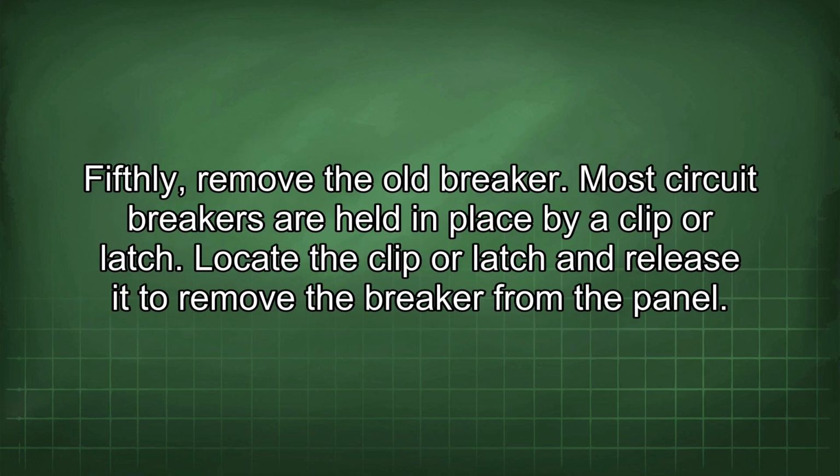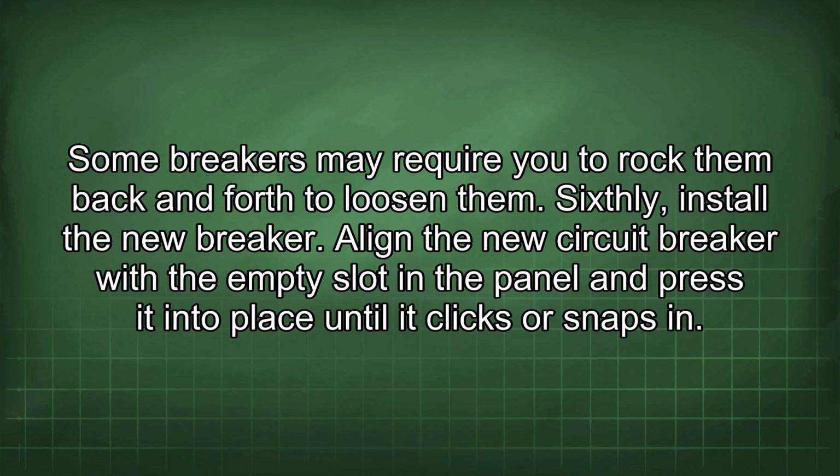Fifthly, remove the old breaker. Most circuit breakers are held in place by a clip or latch. Locate the clip or latch and release it to remove the breaker from the panel. Some breakers may require you to rock them back and forth to loosen them.